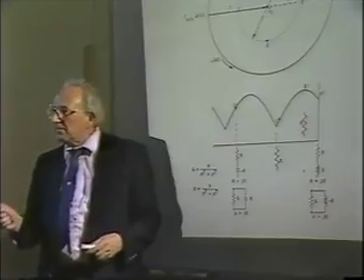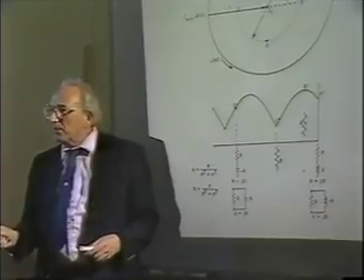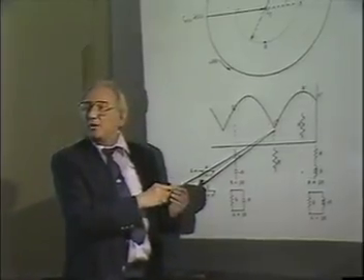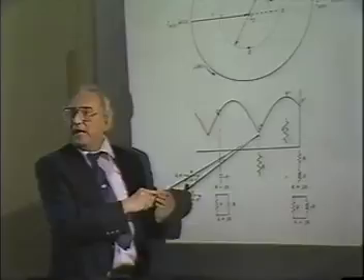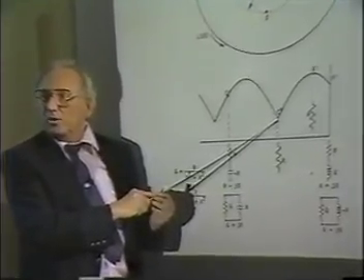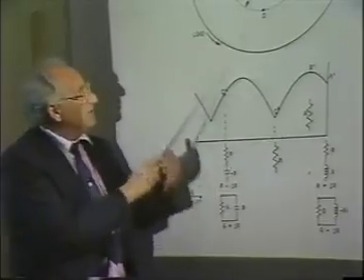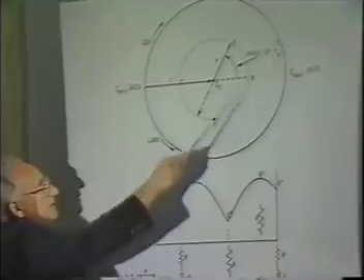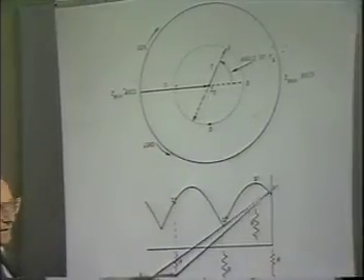I say the first minimum is 200 degrees from the load. All right, here's the first minimum, right? How many degrees away from the load? 200 degrees. How do you find the load? You've got to go toward the load, right? Which is this direction, which means that here's the minimum. I would go around here 200 degrees, and lo and behold, I'd find the load over here.